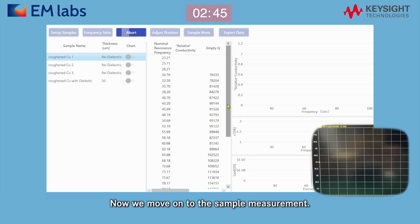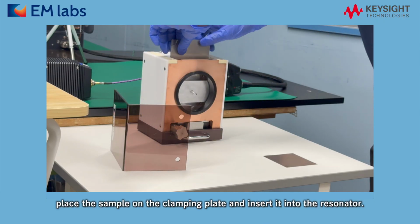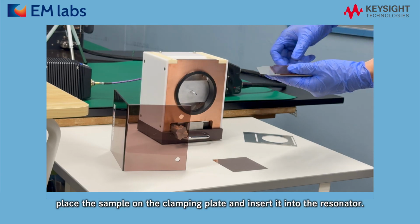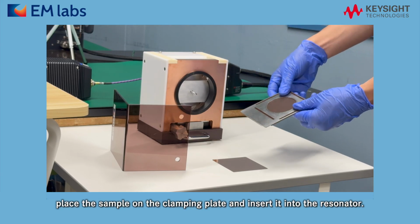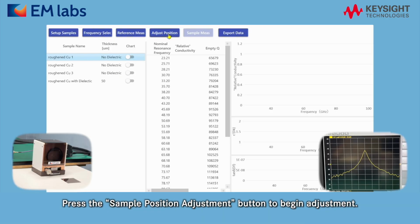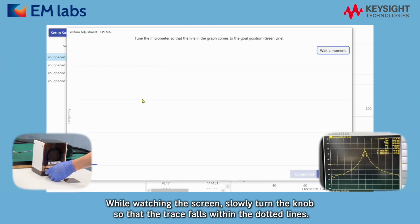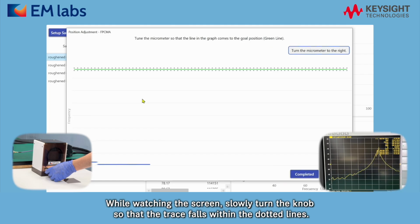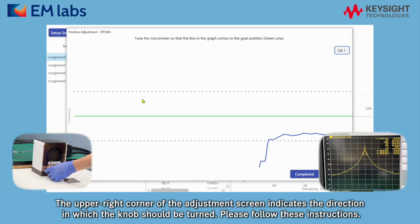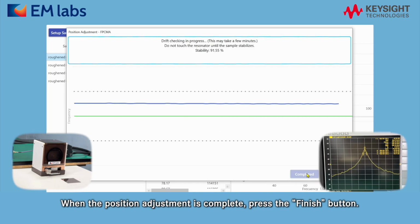Now we move on to the sample measurement. First, mount the sample. As with the reference copper, place the sample on the clamping plate and insert it into the resonator. The copper foil or substrate to be measured should be pre-attached to a dedicated glass plate. Attach the cover for stability to complete the sample setup. Press the Sample Position Adjustment button to begin adjustment. While watching the screen, slowly turn the knob so that the trace falls within the dotted lines. The upper right corner of the adjustment screen indicates the direction in which the knob should be turned. Please follow these instructions. When the position adjustment is complete, press the Finish button.